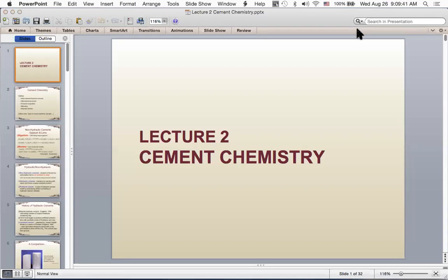For the cement quality control and the X-ray diffraction, yes. Why do we need to do those things if we've mixed the concrete? Shouldn't we know what's in it already? It is a very good question. It is because, as we discussed in lecture number 3 next week, different compounds will react differently with water.